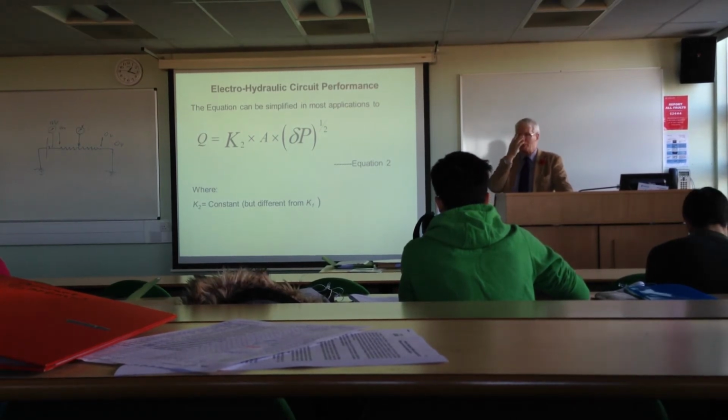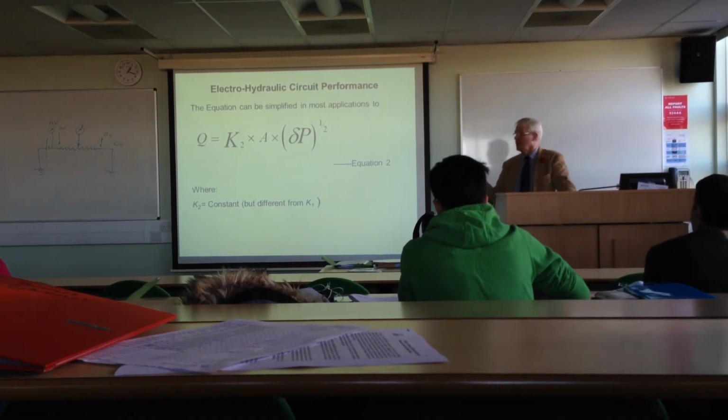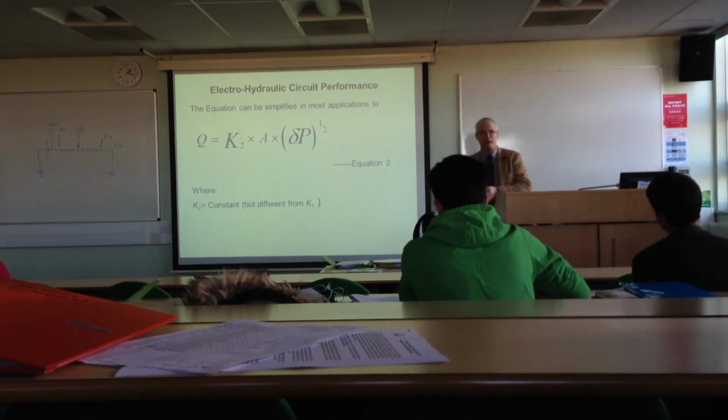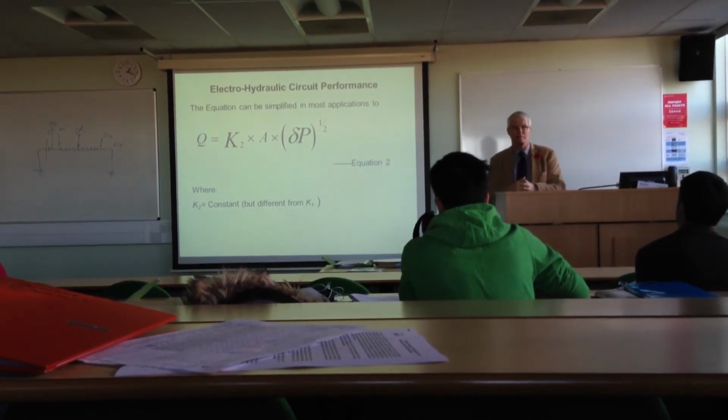One year we perhaps ought to ask a group of students to repeat it, trying to get the pressure drop at 5 bar, and then again at say 15 bar, and you'd end up with exactly the same sort of graph, but the gradient would be different. So you could then program the computer saying whatever the pressure drop is, we've got this lookup table, and we can predict what voltage you need to give you a flow rate.